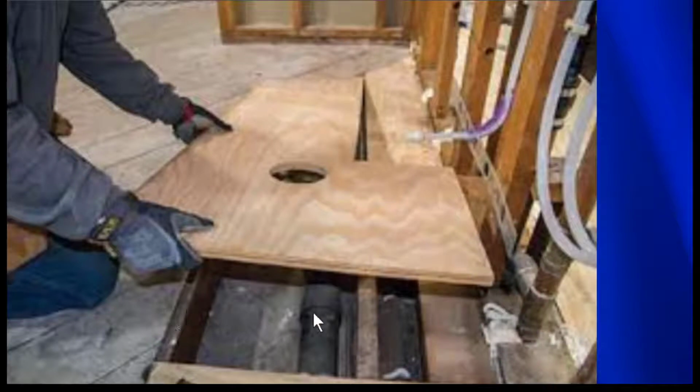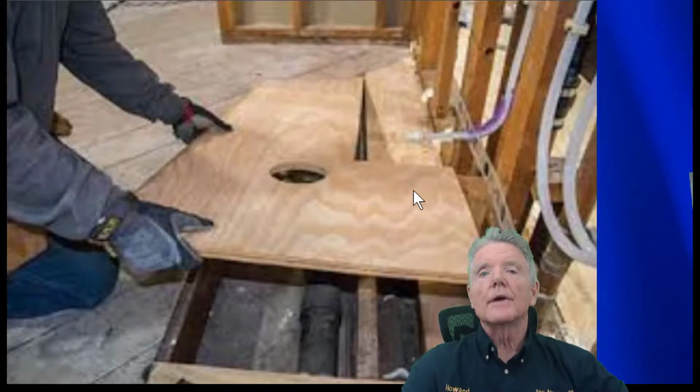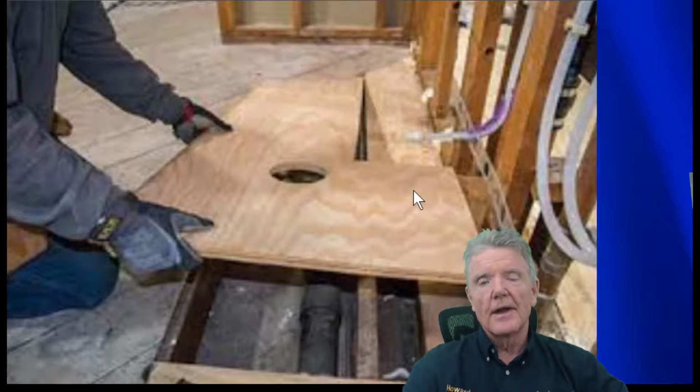So even if on this side over here where the foundation is, let's say there's a bunch of bolts and there's all kinds of plywood and there's everything you can imagine, well, so what? If the earthquake force can't transfer through the floor, in other words, if it can't come this way, transfer all the way out to where the foundation is, it's not going to do any good. Now this floor is extremely important in transference because basically most of the weight of the house is there.